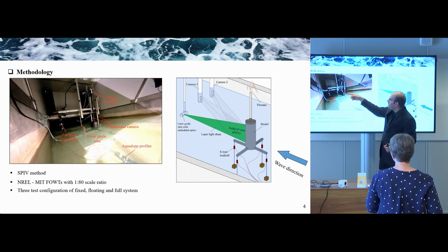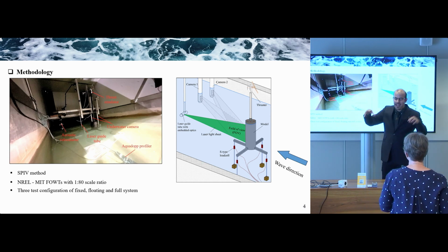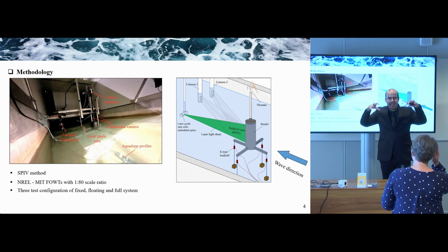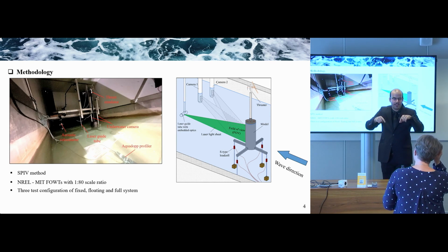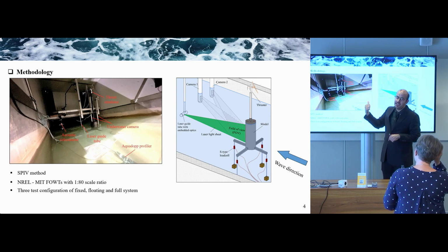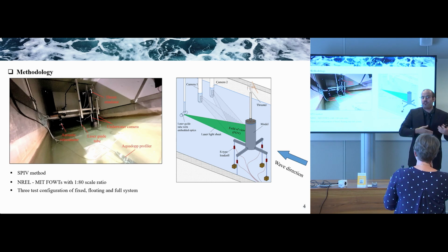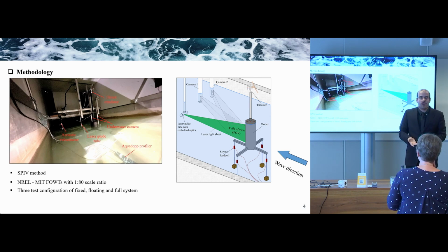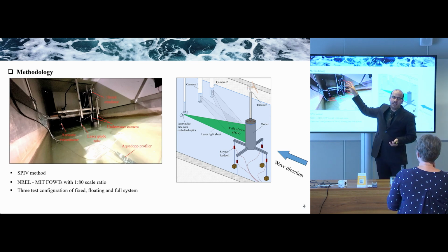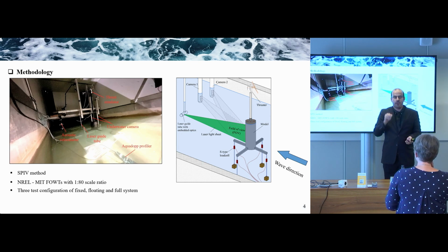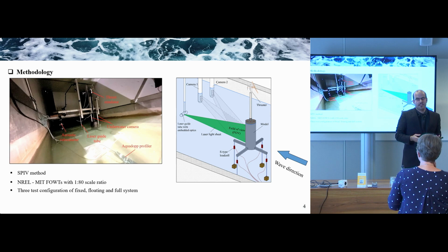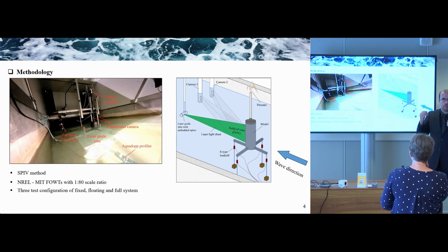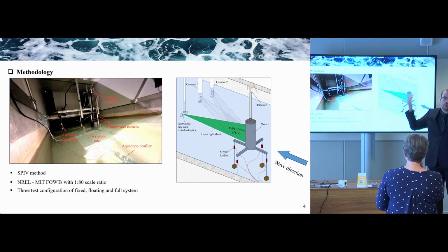But the point was, when we put this cover, we couldn't have the Qualisys cameras capture the movement in the PIV measurement state, so we couldn't use software in the loop or something like that. The feasible option was to use a thrust emulator with a fixed thrust value, which is calibrated based on the rated drag force of the real prototype.